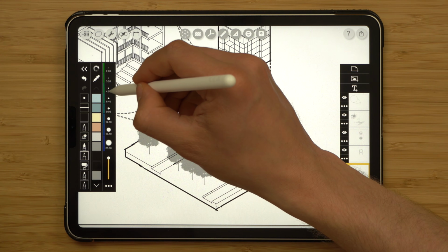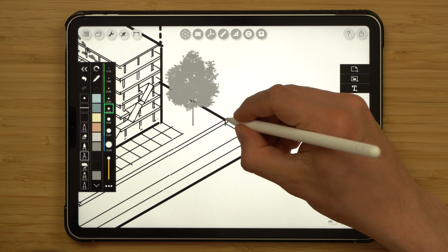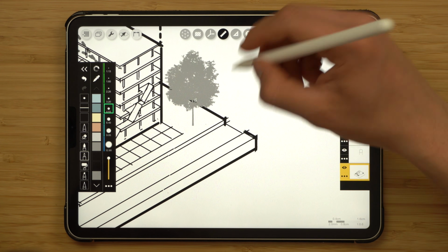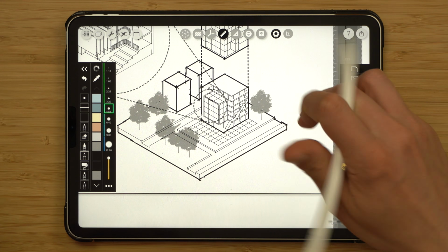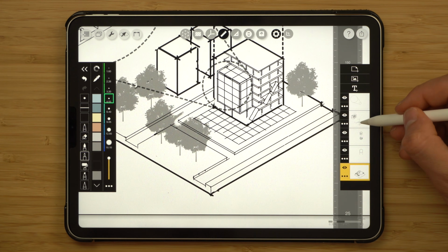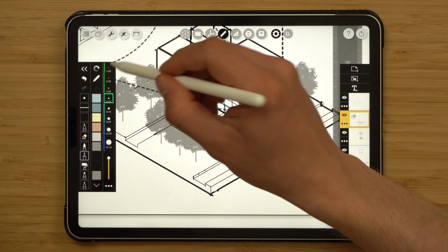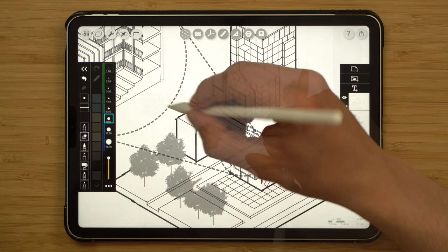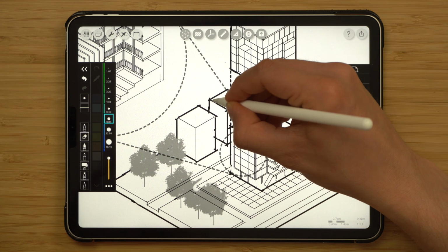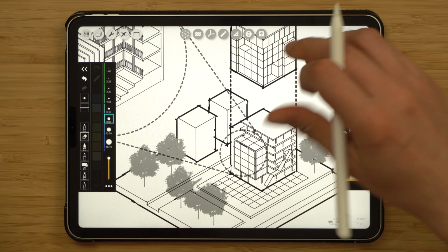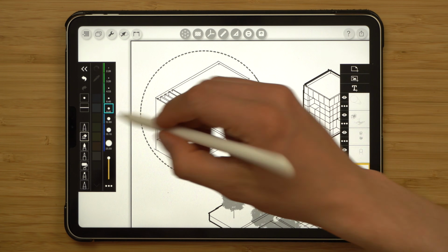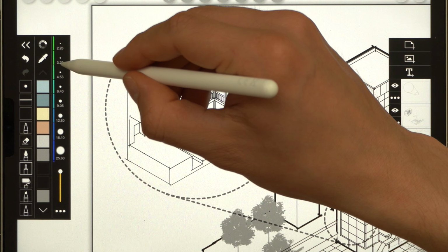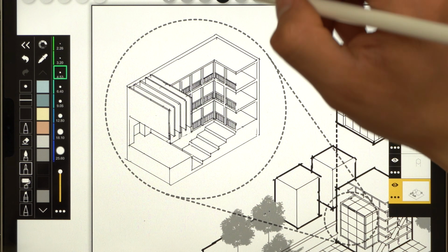Before I do that, I'll select 4.5 points, just so I can remember when I trace over this not to forget this road extrusion here. And then going back to the top layer and going back to 1.6 points, just complete that bit. Actually, I need to erase the middles of these buildings too. I might just do a quick outline of this axonometric with a thicker pen line.